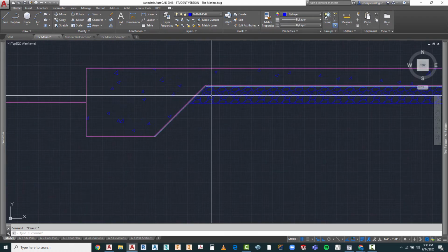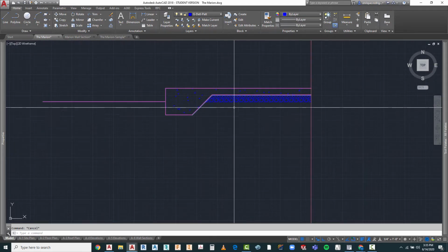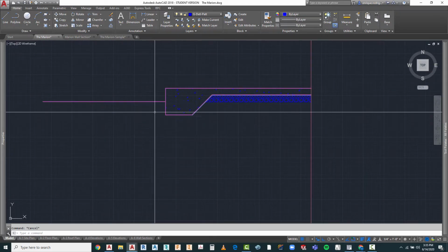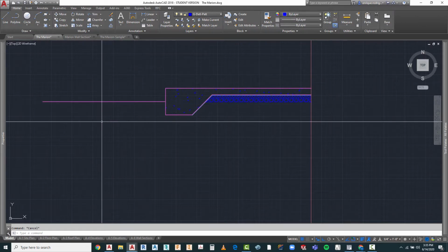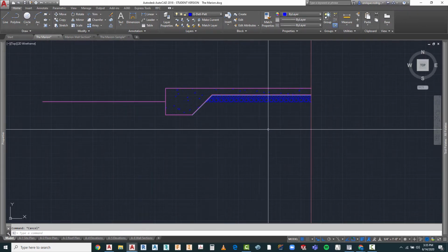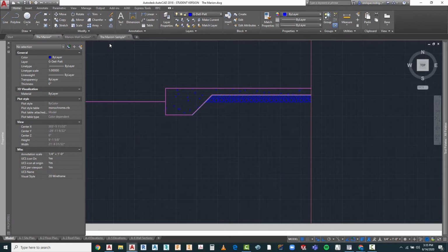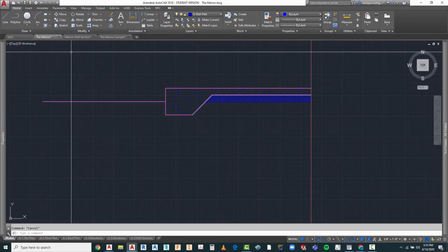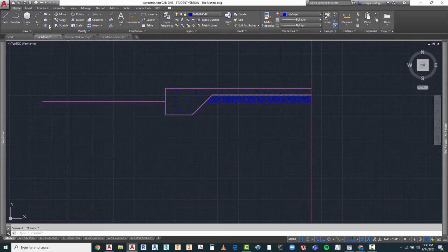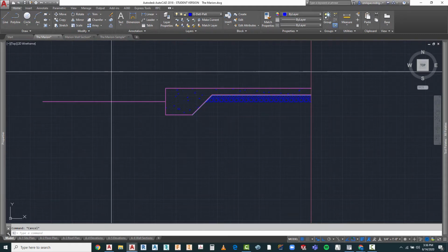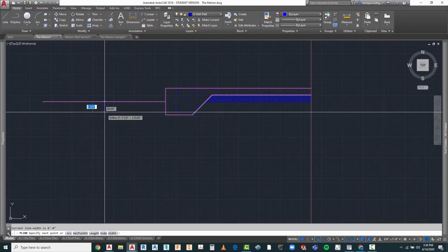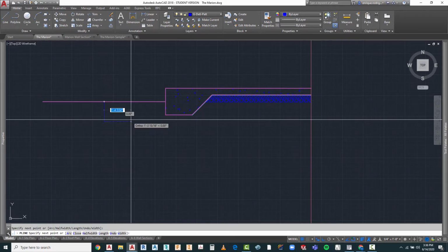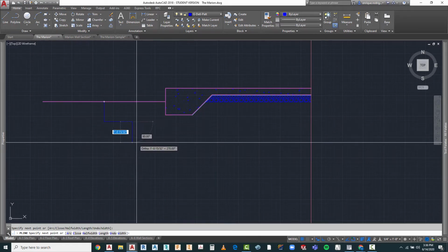So what we're going to do now is also create the well compacted fill that comes around through here. So maintaining the G detail pattern, I'm going to create a border for my earth hatch. I am going to use my polyline command, and I'm going to start somewhere maybe right out in here, and go down, and just roughly.